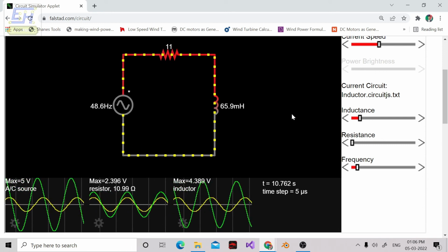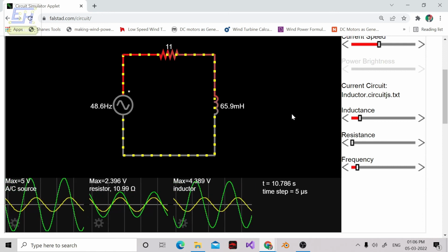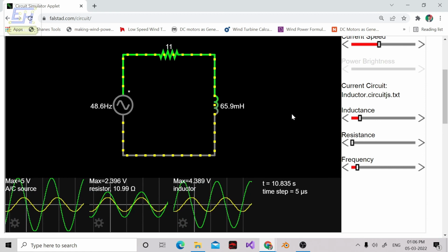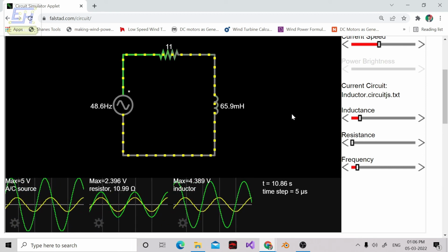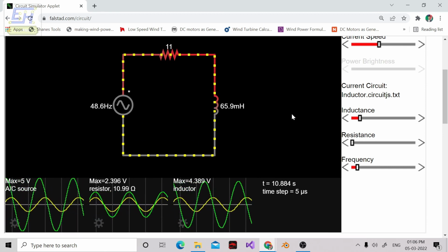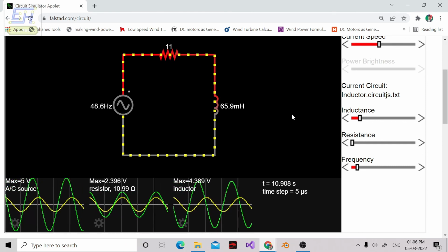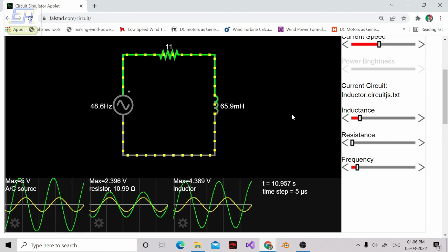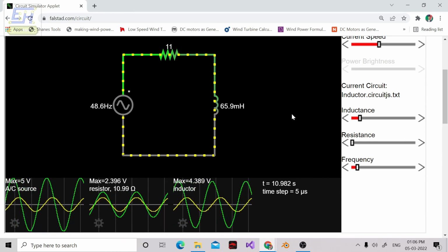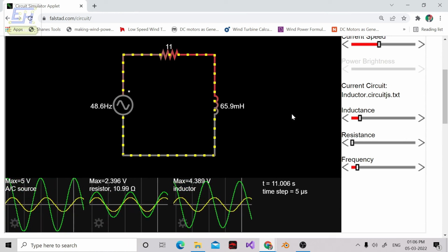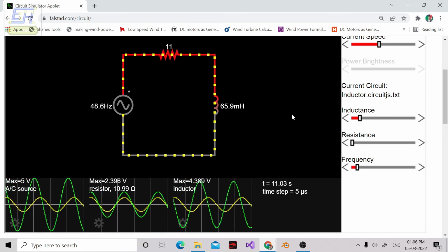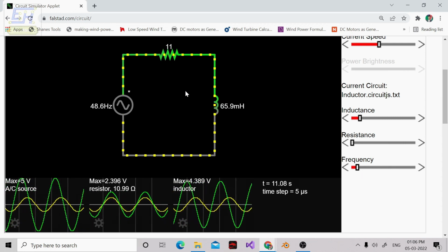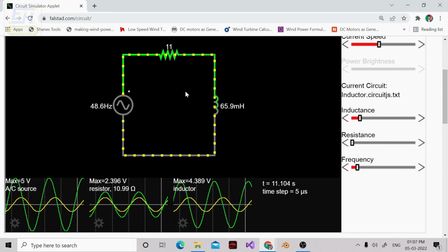So due to these elements, the phase shift will not be perfectly 90 degrees. It will definitely be lesser than 90 degrees, because the phase shift cannot be greater than 90 degrees. Do remember that phase shift in any AC circuit cannot be more than 90 degrees. In the real world the value will be more like 89.99999 something. Or if you are connecting something in series with the element, like a resistor or inductor, then it will be anything between 0 to 90 degrees.